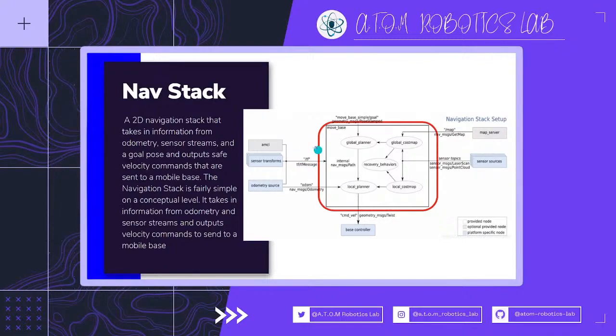From CAD we get all the transforms from all the links we need. After we get the transforms, we give them to the move_base planner, which helps calculate how the bot should move to avoid any collision in the area. We can also perform recovery behavior in this.